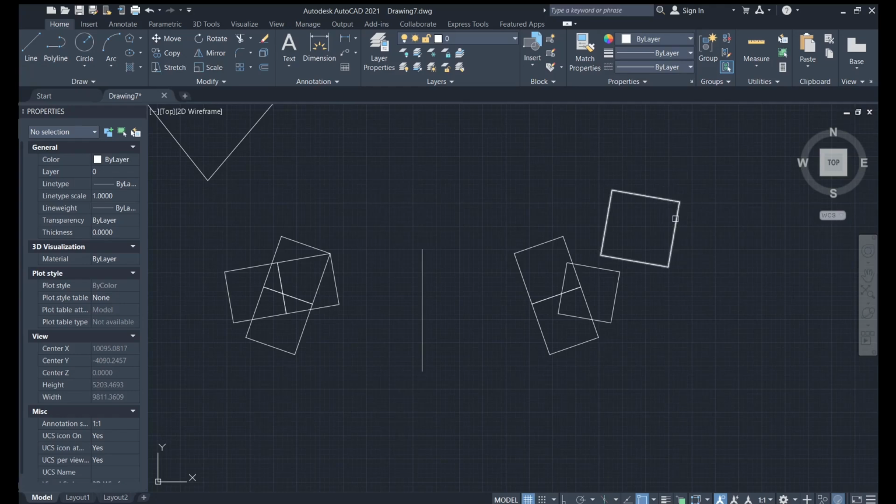Or you can change it by using input numbers. So if I want it to be double, you can type 2, or you can also reduce the size with anything below 1. So you can think of 0.5 as half of its original size. As you can see, when you type 0.5, it reduces it to half. And we can go even further if you want it to be 10 times smaller. You can just type 0.1 and it's 10 times smaller, and it also works in reverse. If you want to increase its size by 10 times, you just type 10 and it will increase back to the original size in our case, or by 10 using the scale.